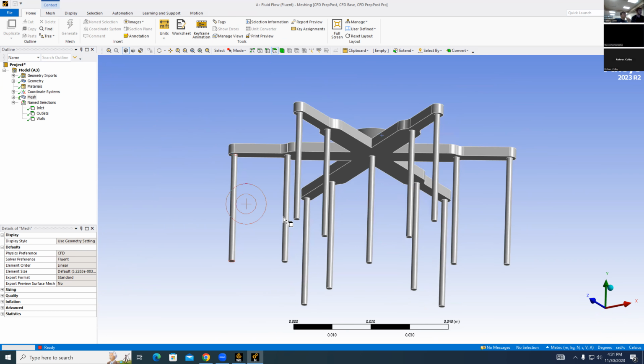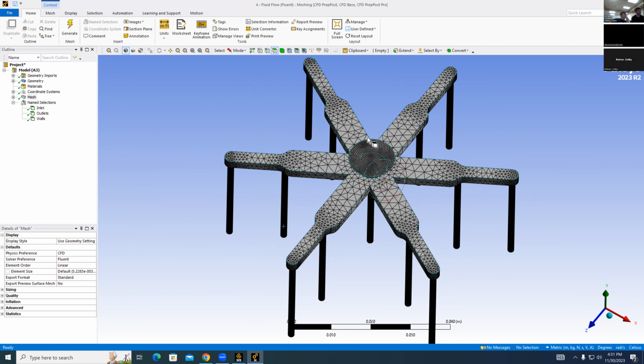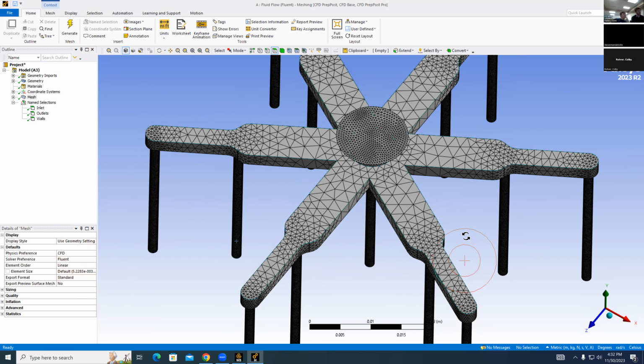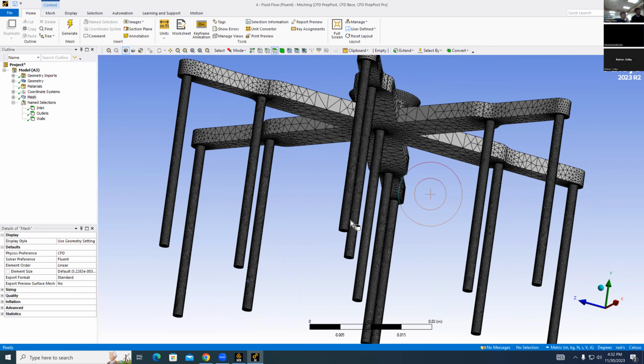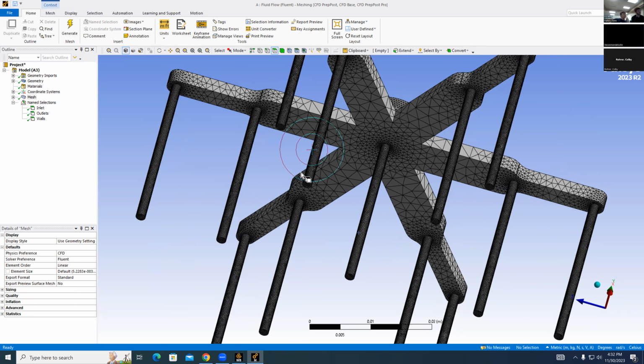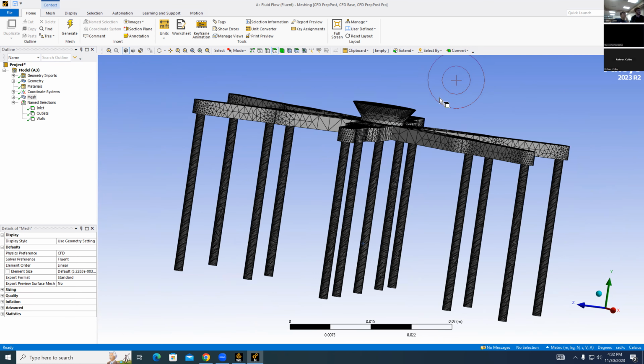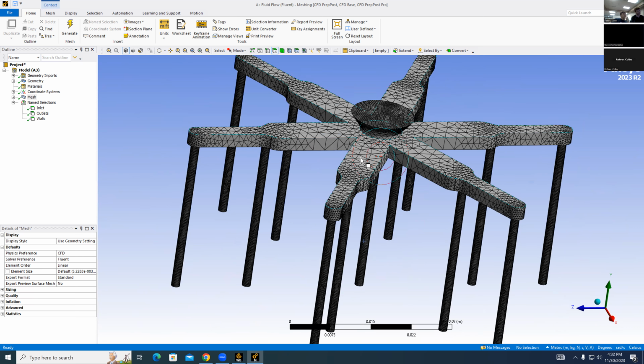and let's do it to our. Did we do it to the whole stem, or did we do it just the end? Oh yeah, great. So now look, that's way more fine than it used to be, and that looks good enough for now. You can do the same thing for the outlets as well. These look really good density wise, so we're not going to do that, but you could. And then we're less worried about these walls, these upper areas, so we're not going to do anything about it. So yeah, now we have our mesh.